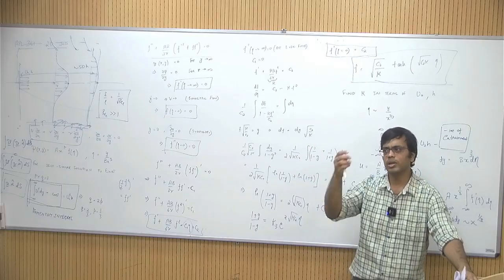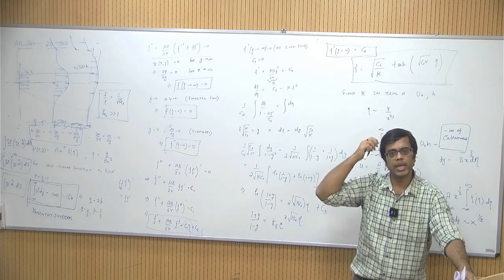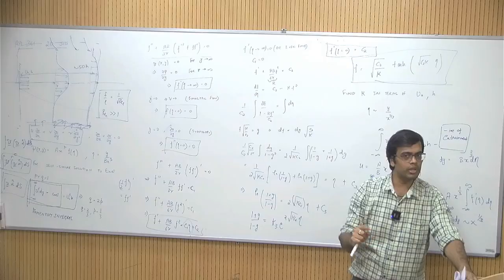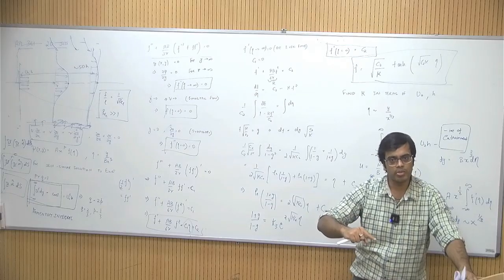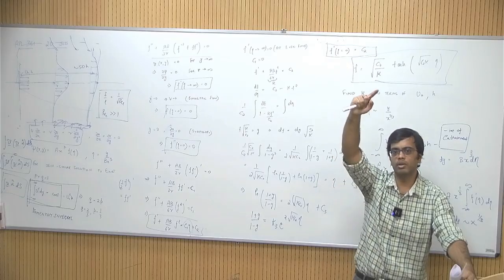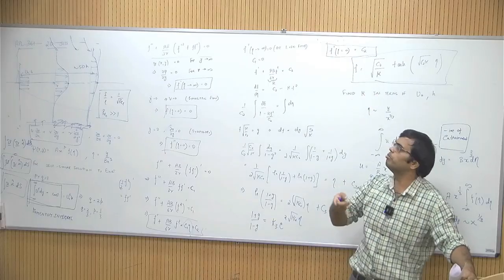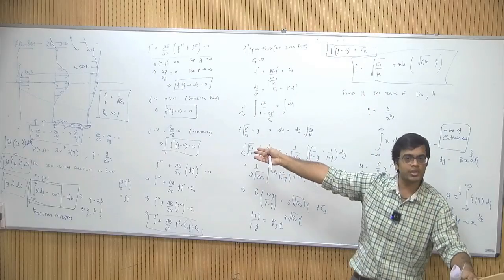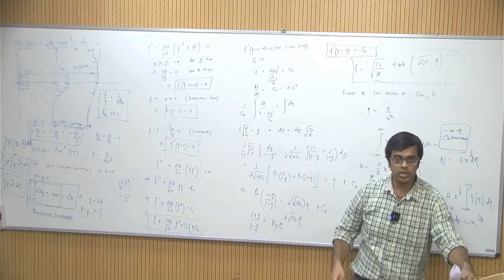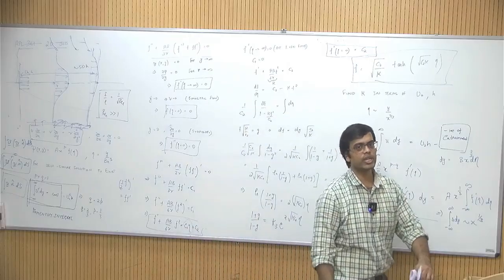If you recall your submerged jet experiment in the fluids lab, you start with a position very close to the nozzle, you measure the velocity radially, and then you move downstream one by one. As you move further away downstream, you are improving the conditions of this approximation. You are making this regime hold better and better. So you can expect that.